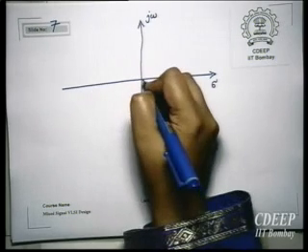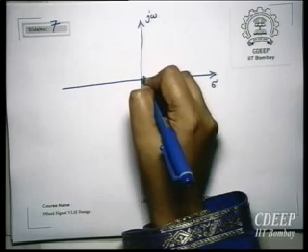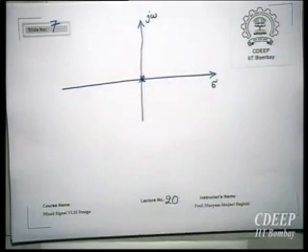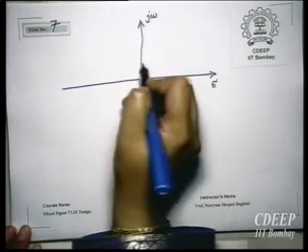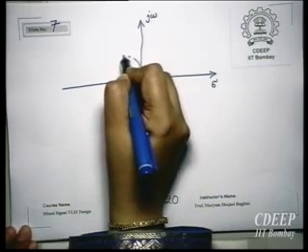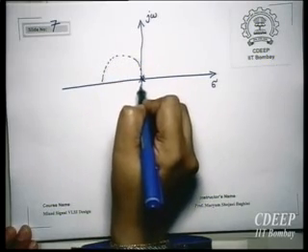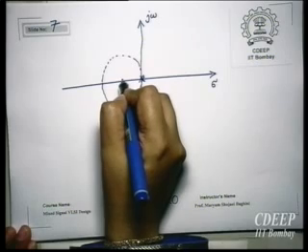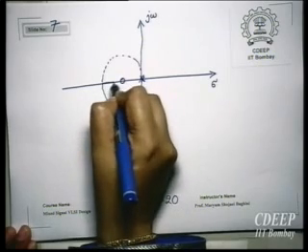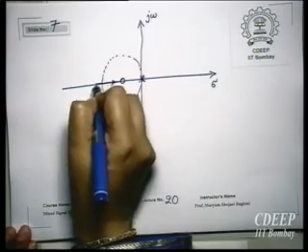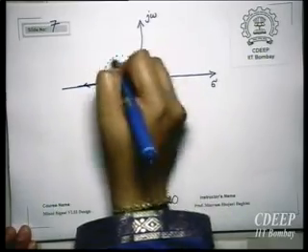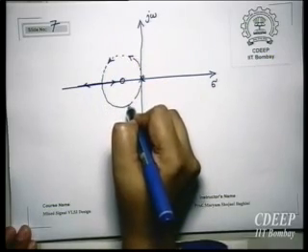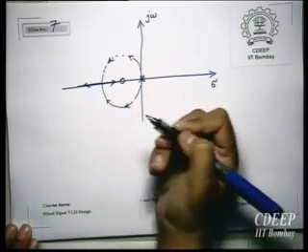If you remember, we had 2 poles at 0, right? When there was no compensation, for type 2, and the charge pump was type 2. Now how will the poles change? You are familiar with root locus, right?